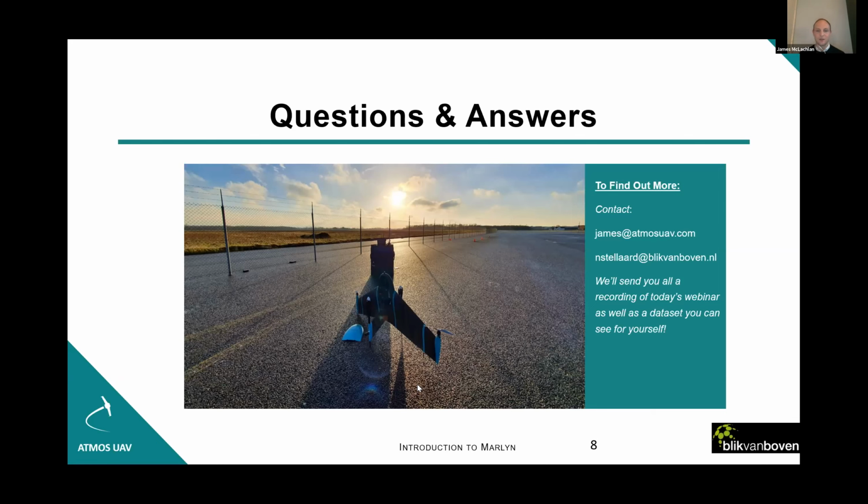Justin Huntley asks, is the system compatible with Trimble equipment? I think that's similarly answered in the last question. I believe Trimble doesn't, as standard, output RINEX data. I'm not sure if you know anything about that, Norbert, but I think we've had some situations in the past where some customers have used it. Trimble has a free to download software which is going to allow you to convert your data from the base station into RINEX, and then it's fine. You just have that extra conversion step.